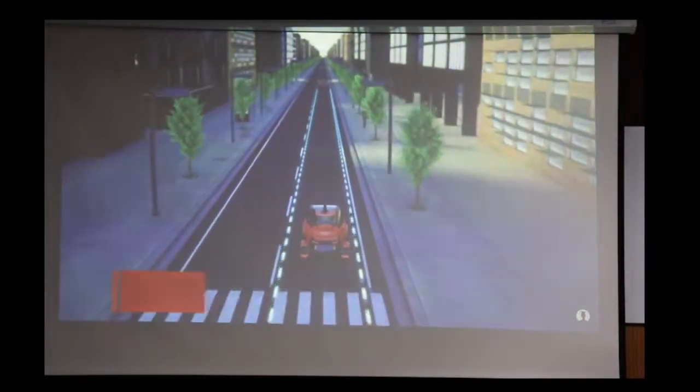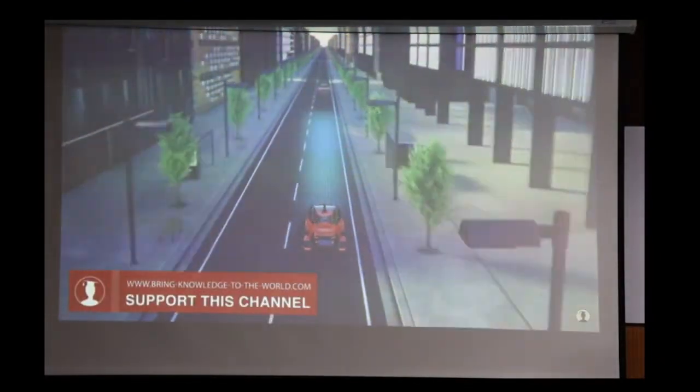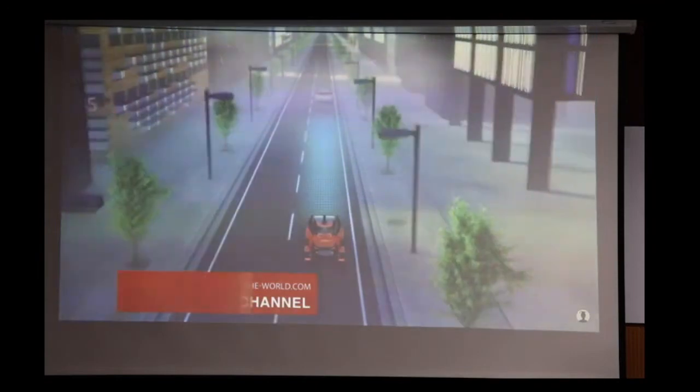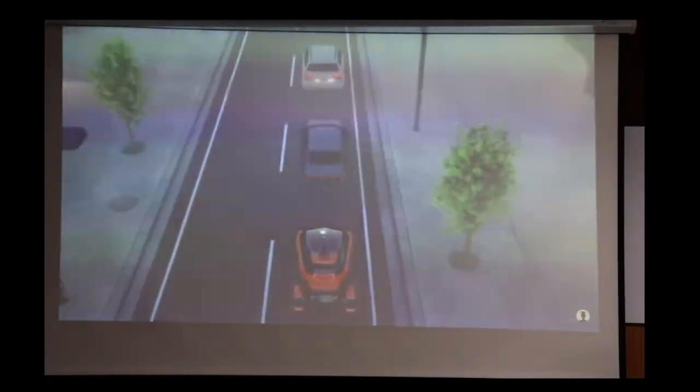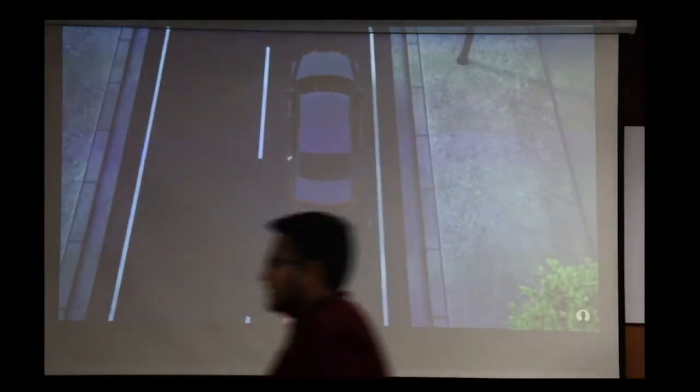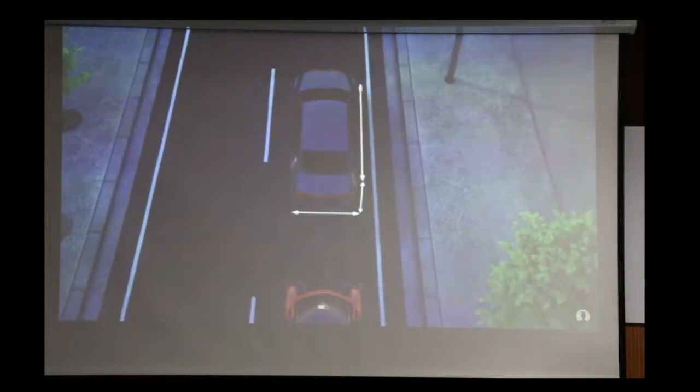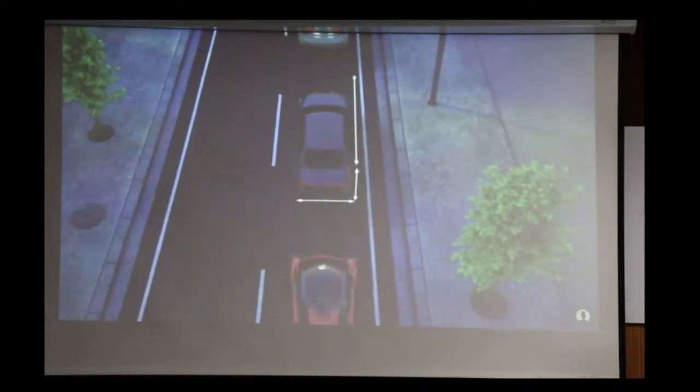Neither LiDAR nor cameras can handle fog. In this situation, radar is needed for forward collision warning and avoidance. A major disadvantage of radar, however, is that the objects must be large enough to be detected. Pedestrians or cyclists may therefore not be recognized by radar.